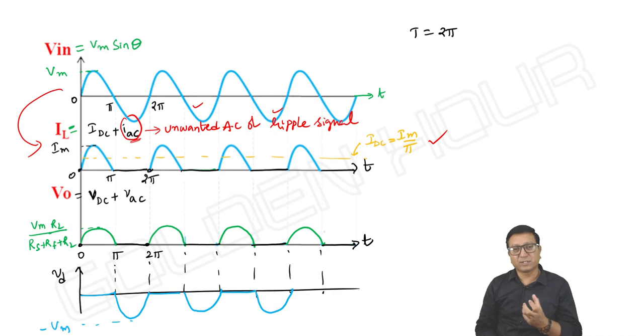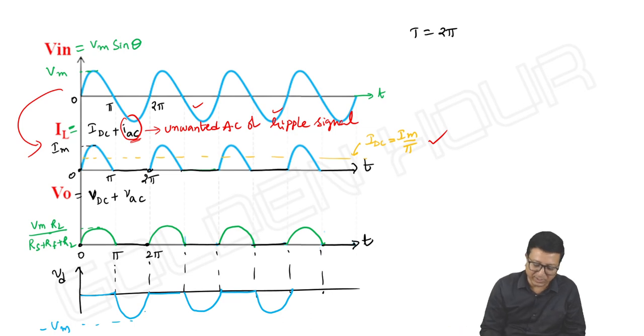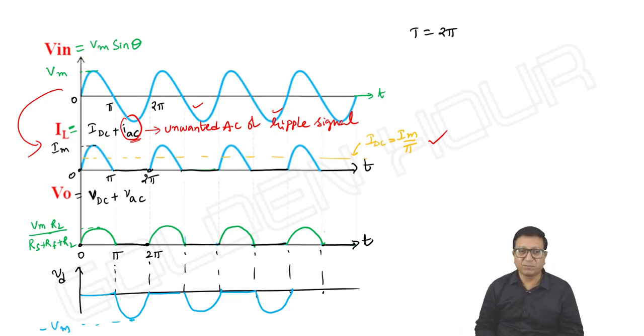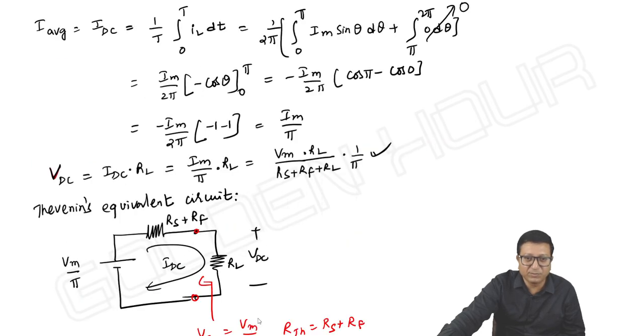So anode to cathode voltage is negative, diode is off. That's the meaning of it. Then peak voltage, what is the peak voltage? That is minus Vm, or the maximum voltage magnitude I am taking, appearing across the diode under reverse bias condition. Peak or the magnitude of the voltage.